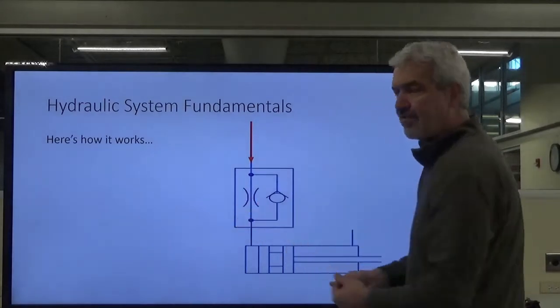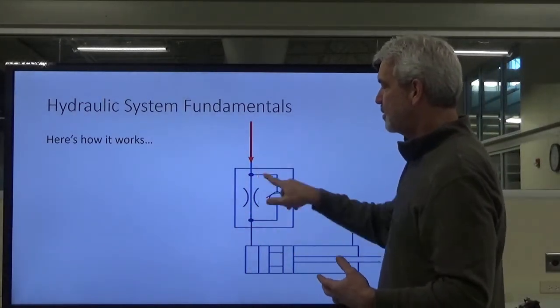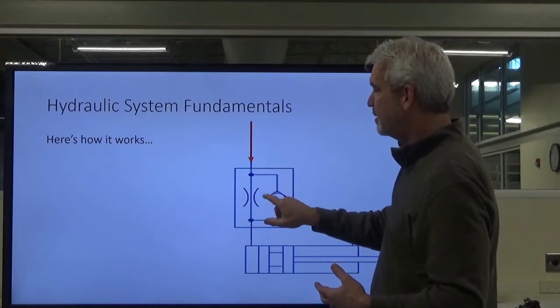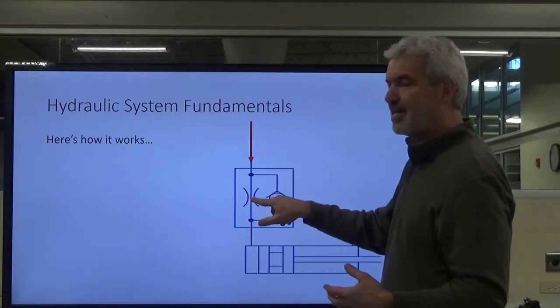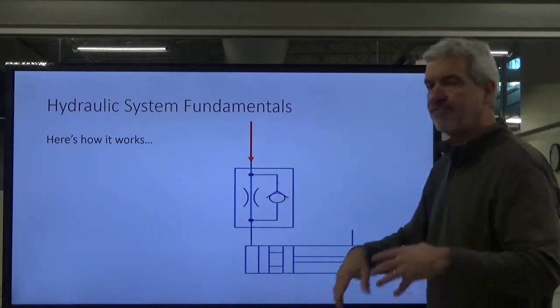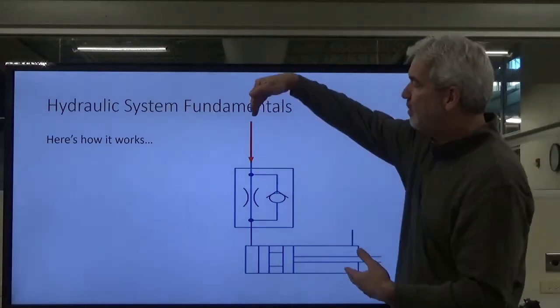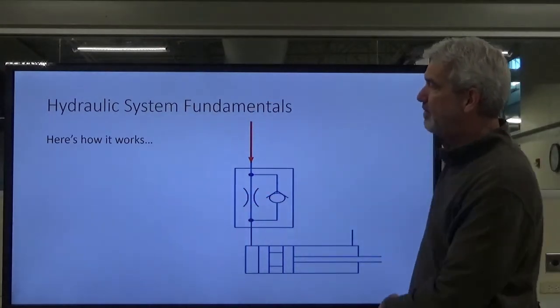And we really won't have any control over our flow, because this is the path of least resistance. There's no control. There's no metering through this. Our metering is done right here. This is the most resistance, so it's going to go through here and just go full flow into the backside of our cylinder, okay? That's with the fluid flowing in this direction going into the valve.